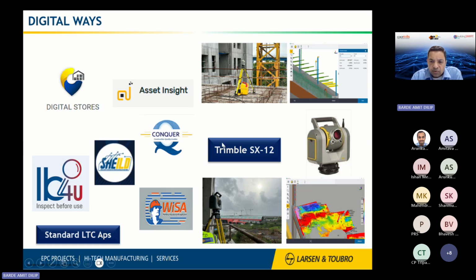Advanced tools wise, of course, you see this Trimble SX12, which is interesting. We have been using it for a couple of projects now, where all your surveying needs, digitalization needs, levels, misalignments, dowels. If you see this right hand side top picture, precast has dowels, and those are extremely sensitive. We are tracking at almost plus or minus 3 millimeter. Otherwise, the next panel would not fit.